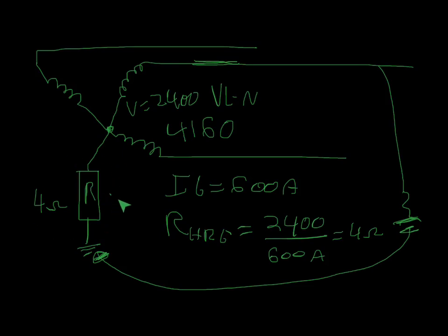Next thing is, just with a meter, you can check the resistance of the resistor here. Just make sure that it matches the nameplate, and then you should be good to go.